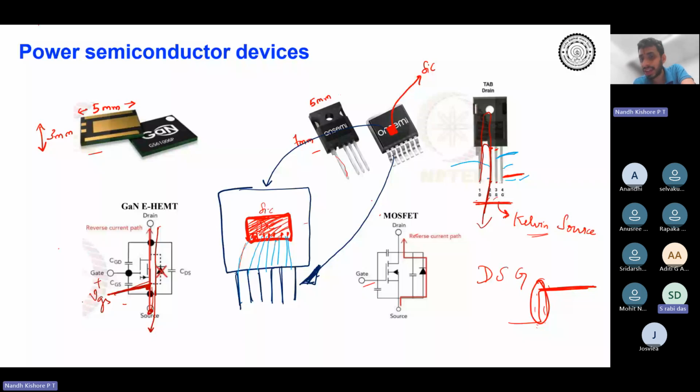No, that is why I'm telling: they are internally shorted. Because if you take some random device, take a multimeter and check the continuity of terminal 2 and terminal 3, it will show you a short. Okay, they are internally shorted. No worries.